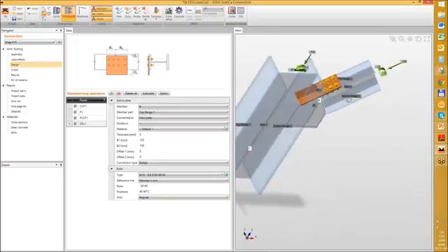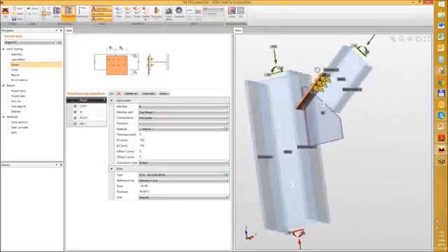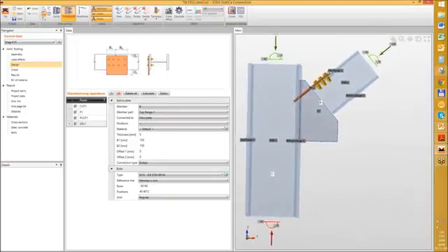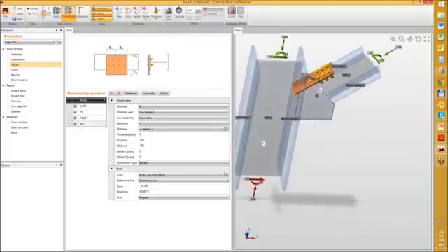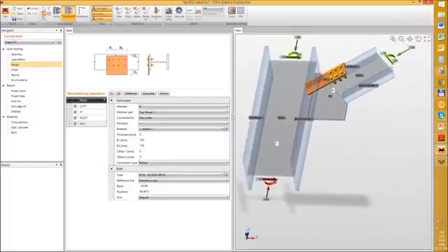Maybe like that, doesn't matter. So we have bolts on this splice, and now we have to cut the splice by member and weld it, and also we have to resolve this detail, this collision between these two plates.